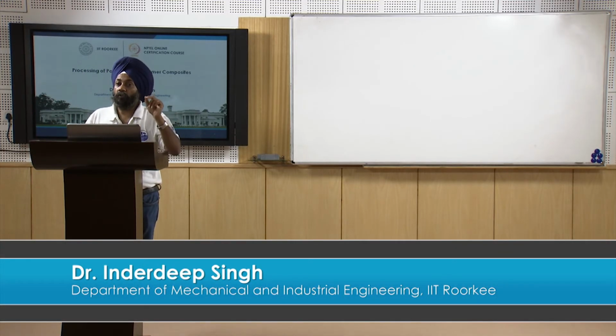The curing process may take 6 hours to 8 hours, maybe sometimes 24 hours to complete, and after curing we get our solid product because the polymerization process has been completed, although we added the hardener and the catalyst in the epoxy or in the thermosetting resin. So the curing cycle is sometimes very long, but here partial curing is happening, and that has to be done within that time window only.